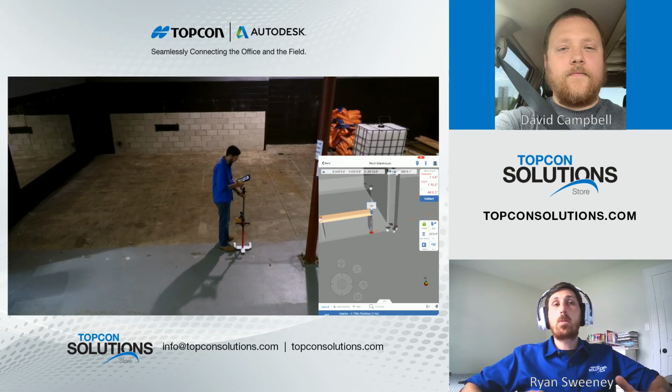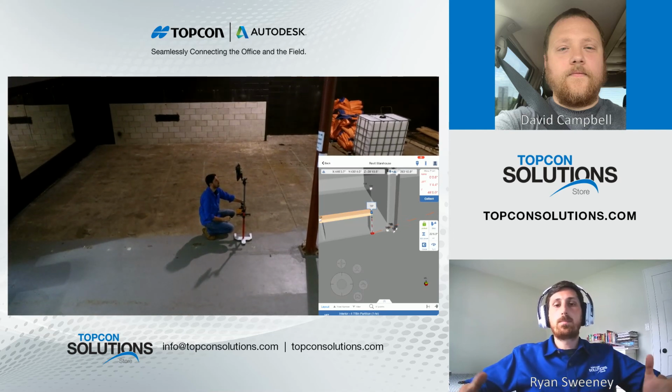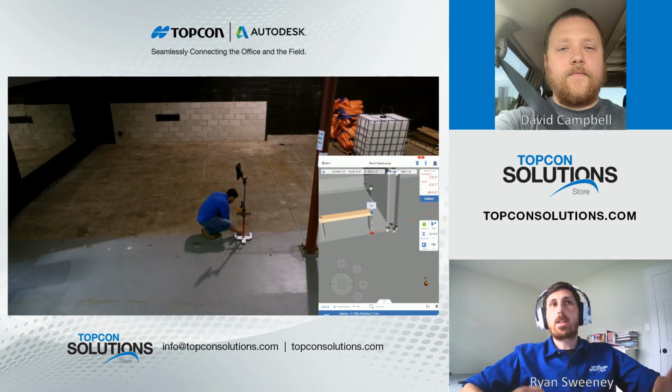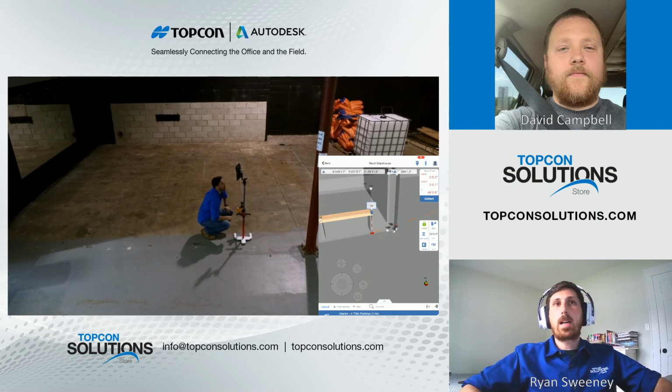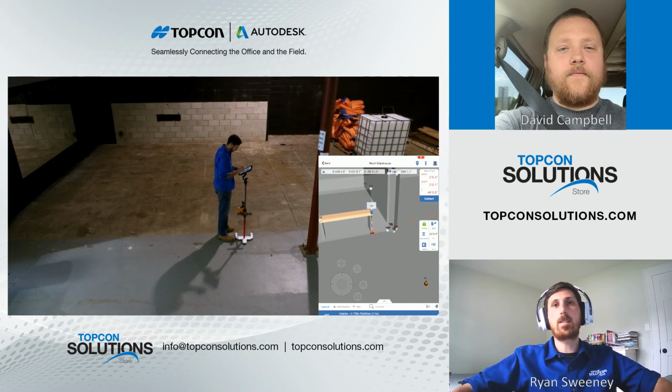So now we're going to move on to just laying out another point. The nice thing about using the XY positioner, which you can see here, versus a typical 2-meter rod pole or adjustable rod is the fact that this uses the laser pointer as the tip. You have right here, we have a 360 prism screwed right on top of a line laser or point laser. And where that point hits on the ground is exactly where the point you're trying to lay out is. So if you're on a sloped surface, something corrugated, you can still make your mark on that surface without having to worry about the tip of that rod slipping or sliding, or, did I actually hit that tip or not? This is going to give you a nice focused beam so you can just make your mark right there and keep things as accurate and as tight as possible.